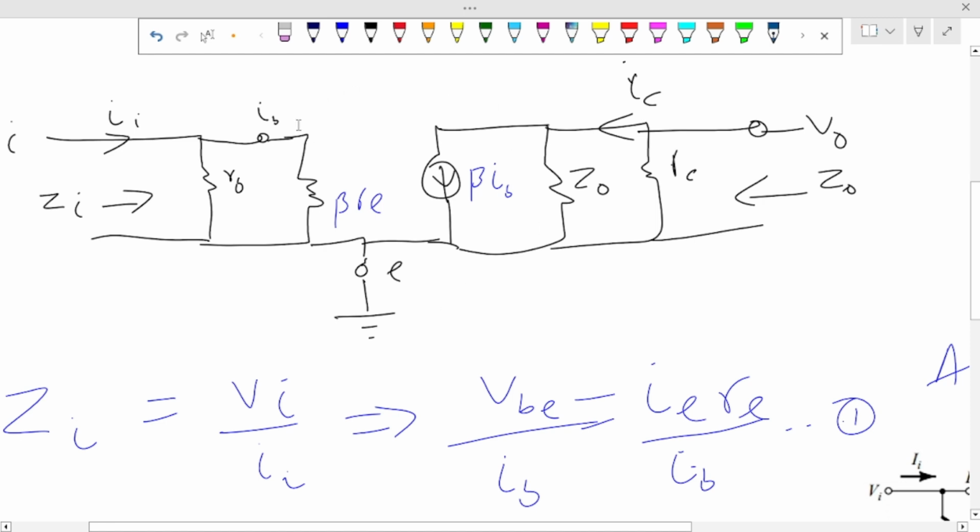This point is regarded as a system, while we have a two-port network: a terminal here, positive and negative, another terminal here, positive and negative. Usually you should have the input coming this way, output going this way. But if you look at our arrow, the input is coming out here, and the output, which is supposed to go this way, is coming in. Now, because we put our arrow this way, we are going to have a minus sign when doing our calculation. Bear that in mind. We'll bring this back when doing a calculation.